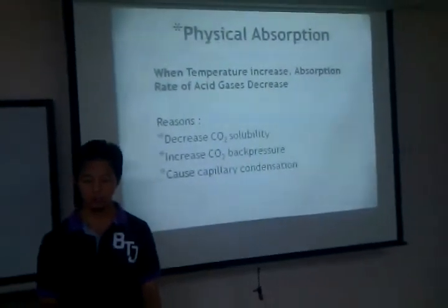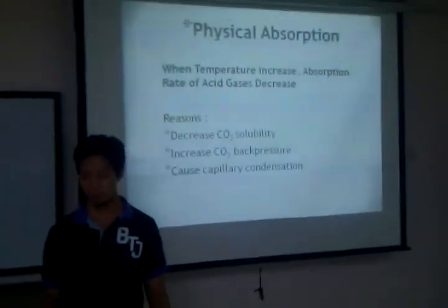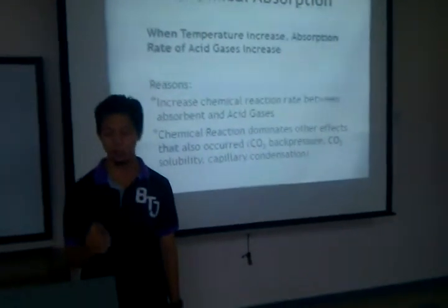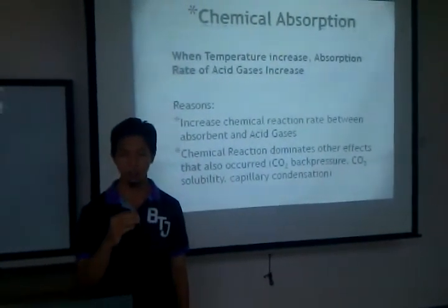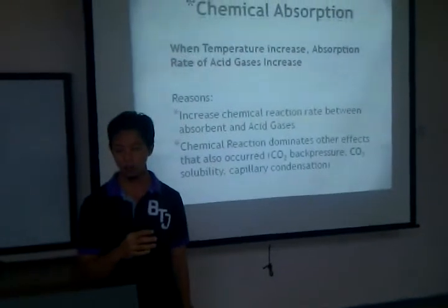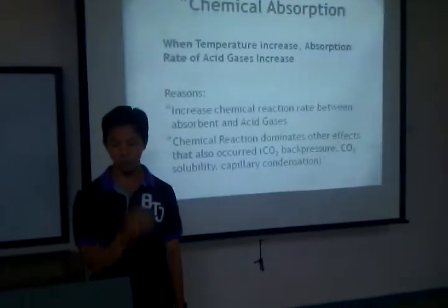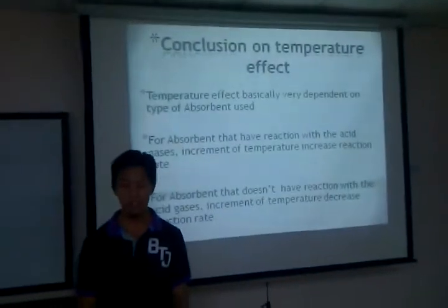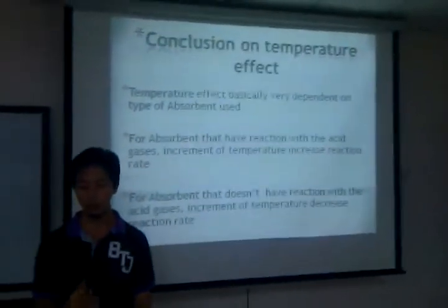And the third reason is that it will cause capillary condensation, where CO2 will turn into vapor and fill membrane pores. For chemical absorption, when the temperature increases, the absorption rate also increases. This is because for chemical absorption, there are chemical reactions between absorbent and the acid gases. Even though there are also effects of CO2 back pressure, CO2 solubility and capillary condensation for this absorption, the chemical reaction will dominate the other effects. In conclusion, we can say that the temperature effect is very dependent on what type of absorbent is used.